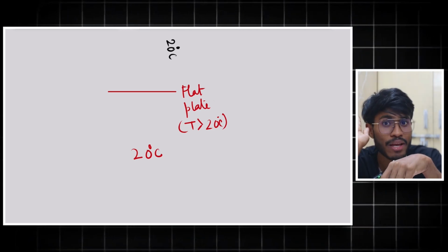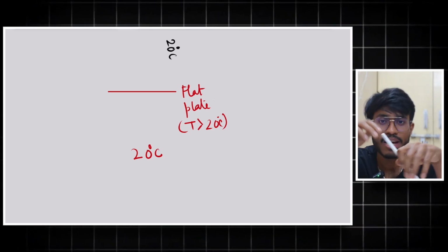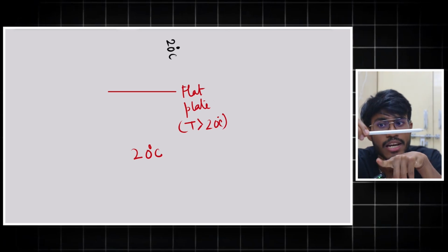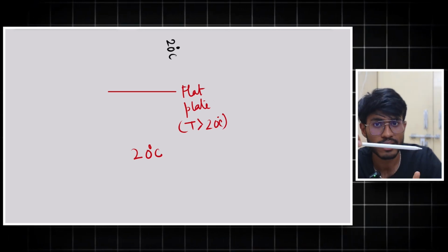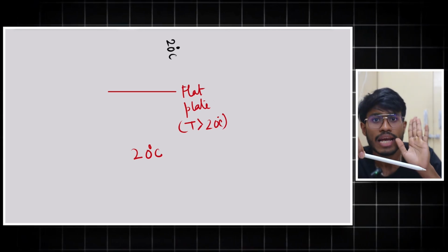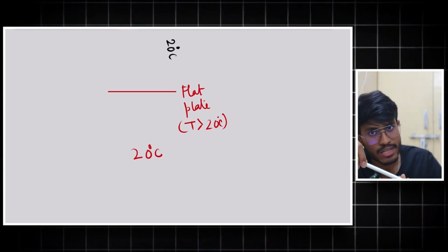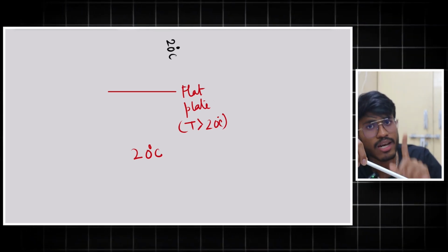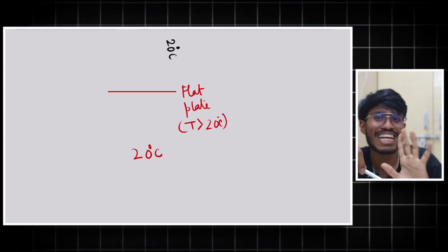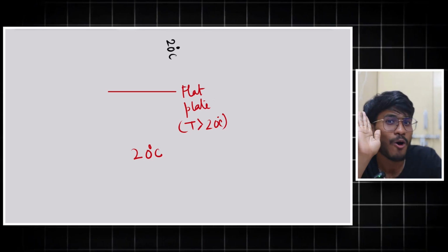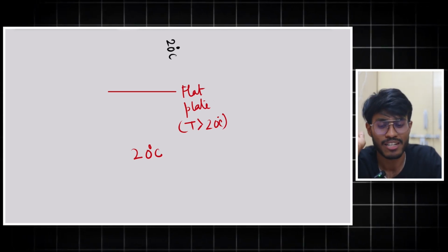I think that I am able to convey the concept to you. That is because the airflow is hindered, and convection means heat transfer augmented by airflow. So airflow is hindered, that means heat transfer is hindered, that means there will be less heat transfer. So this is the only concept that you need to understand.